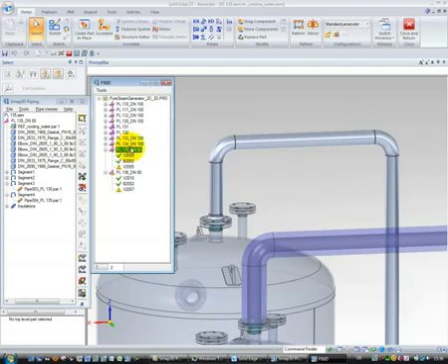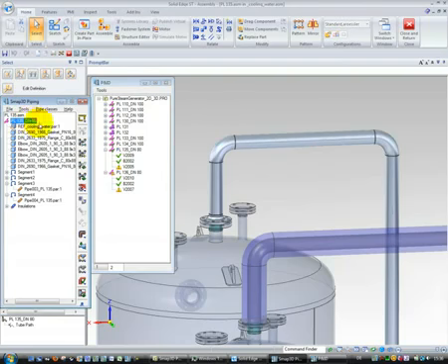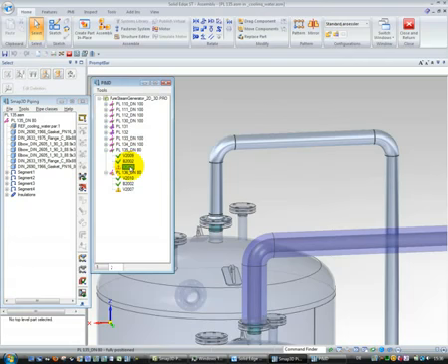The pipeline in 3D is also generated. We see in the piping mask all the required fittings and pipes. And from the PMID we get delivered that one additional component is missing now, because here we do not have a green check visible in this mask. So when we click on this entry, we can see the information that transferred from PMID to the piping or 3D environment, and here we can read that this, for example, is a valve.